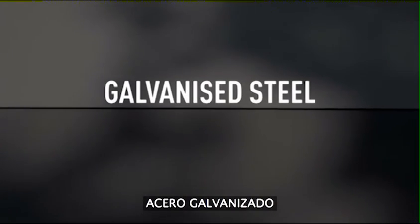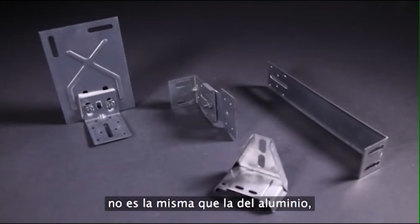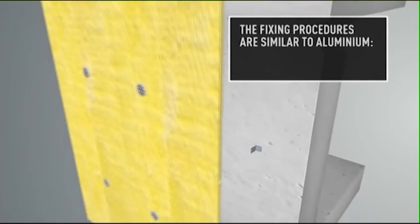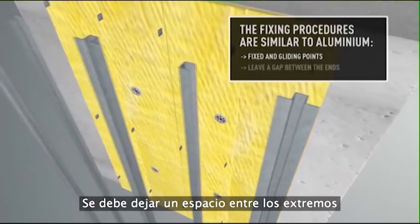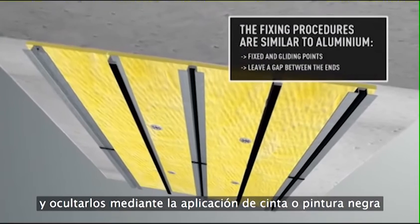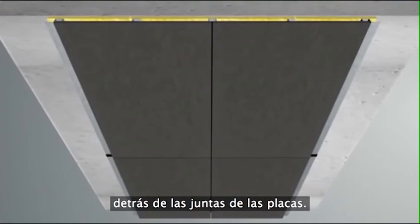Galvanized steel. Although the thermal expansion of galvanized steel is not the same as aluminium, the fixing procedures are similar. The wall brackets are still arranged as fixed and gliding points. Leave a gap between the ends of the vertical Omega and U profiles and conceal them by applying the black tape or paint behind the panel joints.